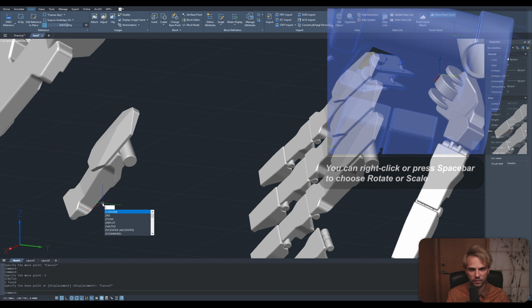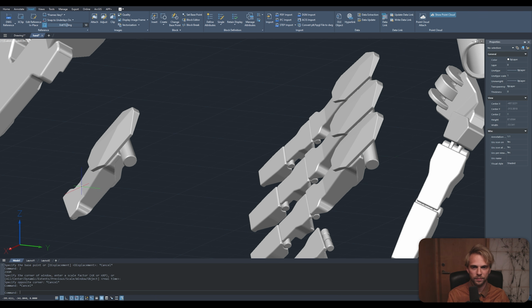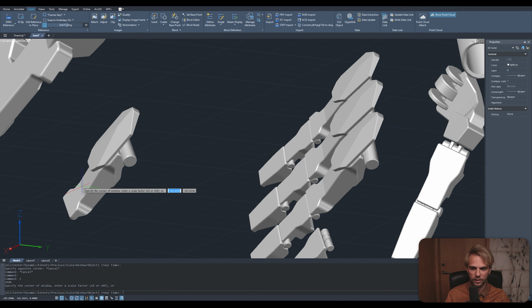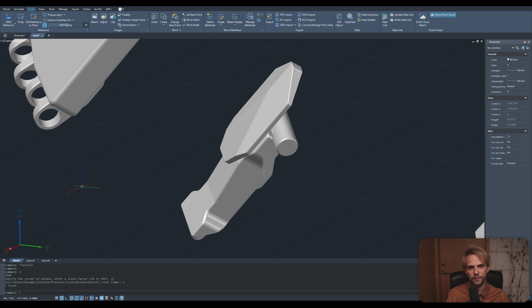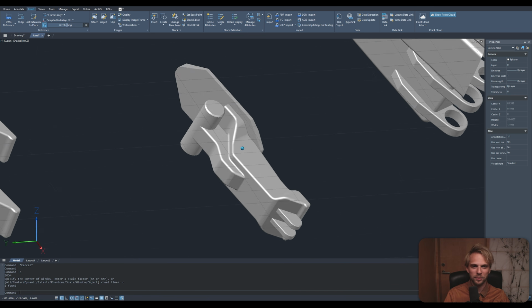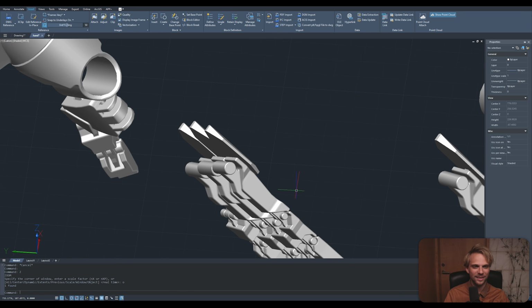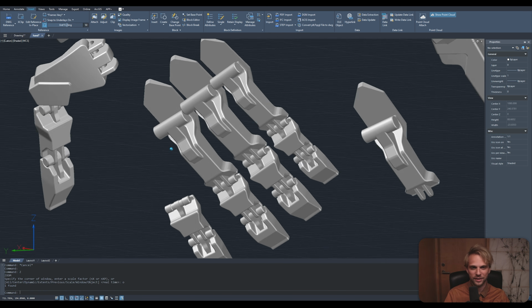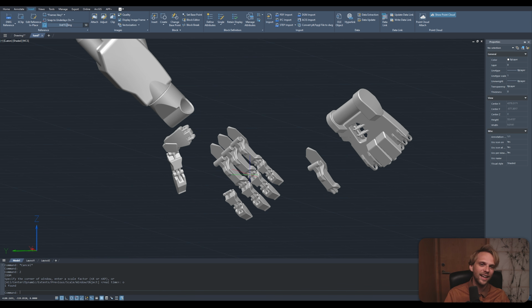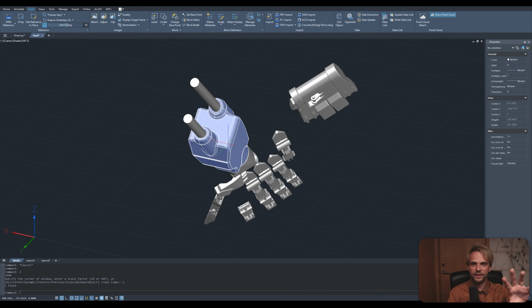Sorry, Z enter, oops, Z enter, O enter, zoom to object. Sorry, the muscle memory is not there. I'm too used to other different software packages, mainly Unreal Engine these days. So that's it about the 3D model handling improvements in ZWCAD.